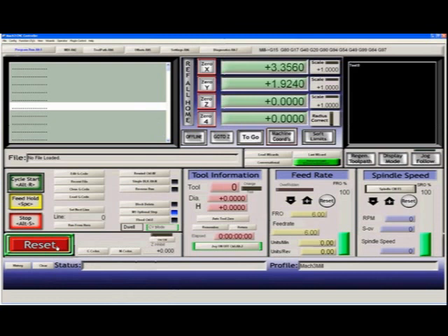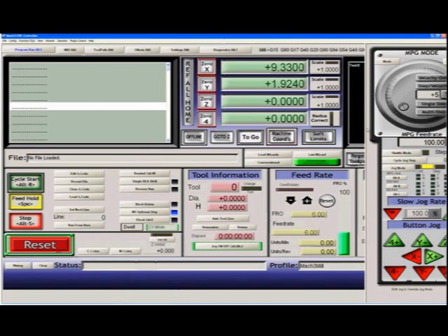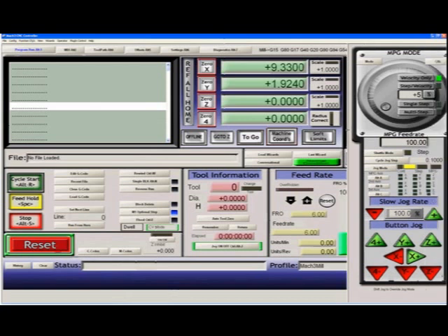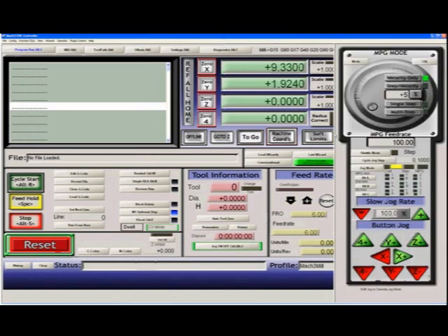Now a secondary complaint is, okay, my motors move, but they move very slowly when I jog. Why would that be? Well, as you can see, if I hit jog, I'm going at 120 millimeters per minute on this system. If I hit the tab key to bring out the Jog Tab, and incidentally, to control the Jog Tab, drag it out so that it is on your system facing you and you can read it fully, tab it in, tab it back out, and it will remember its location from then on. The jog rate down here at the bottom, you can see it's set to 100% on mine. That can be set to any value, so make sure that it's set to a value that you want it to be for your slow jog.